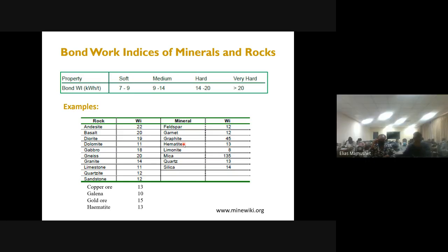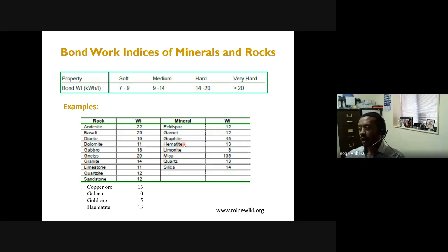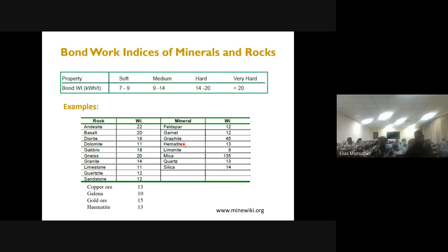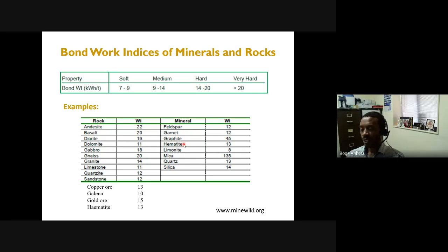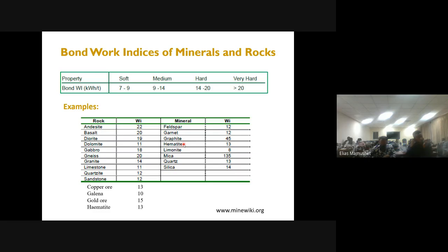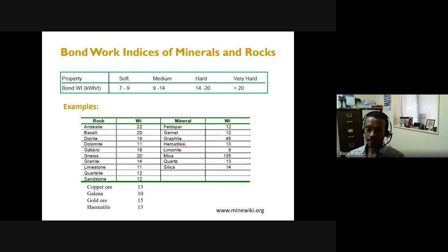What about for laboratory level? Yep, so these are actually lab-based equipment, mind you. So we are testing the grindability or the crushability of an ore in the lab. When I say bond work index, these are conducted in the lab on small scale equipment. The drop weight test also uses specialized equipment, but this is conducted in the lab.